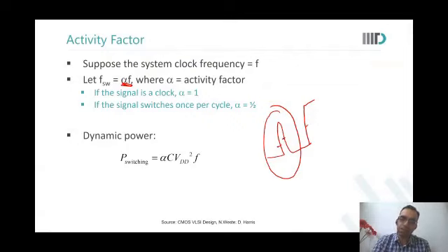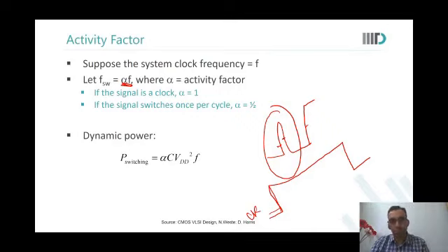So the clock is here. Let us say this is your adder circuit, some node in your adder circuit. It had a glitch, carry out, let us say. It had a glitch and then it rose to 1. So what is the glitch leading to? Where's the by 2 factor coming from? 3 is because of 3 transitions. By 2, why would it be by 2? Because every transition is 1 by 2.